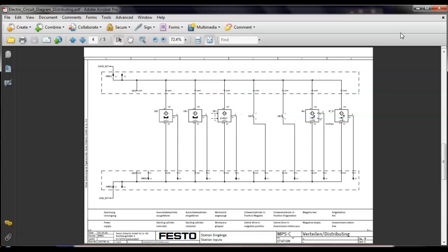So you have to make sure you figure that out. Or look at the diagram, find something that's electronic or requires power. Obviously, power is important. That's the plus. Plus comes down to the PLC, which has to be sinking, right?